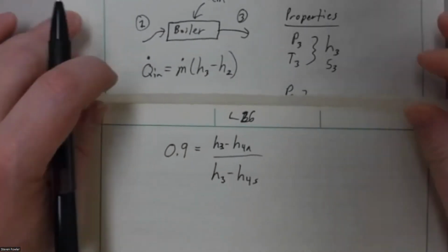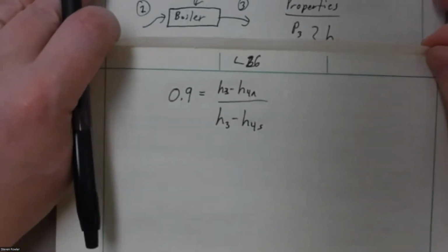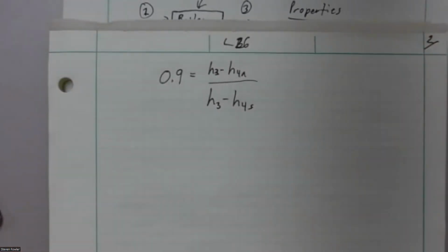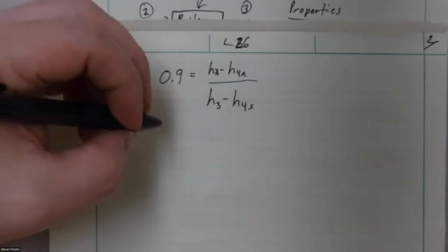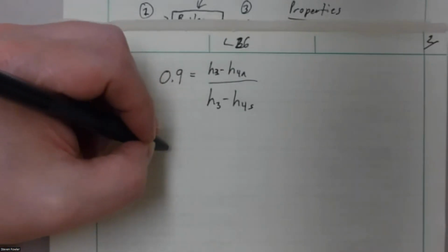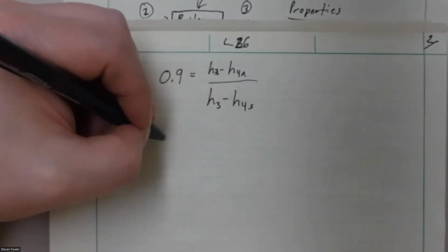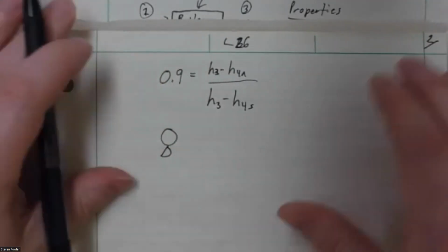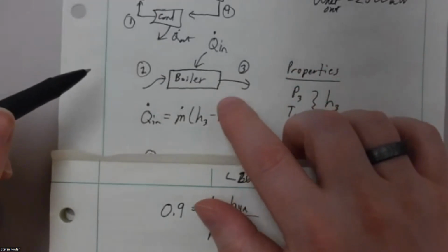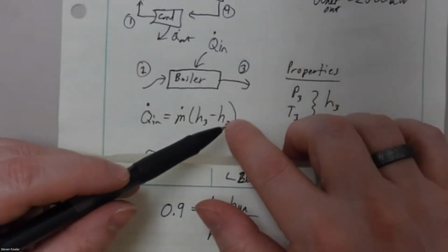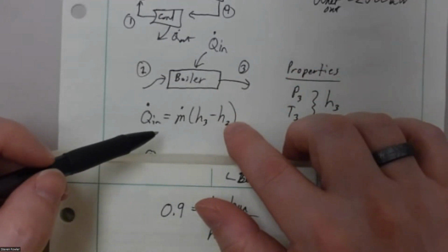Now, this is how a lot of times with the Rankine cycle you want to approach it: just start looking at the individual elements. What can I find with the individual elements? Does that get me a clear path back to a final solution? Mathematically, it's not a lot more complex than what we've already done. It's just that now I've got 4 different states I'm processing, so I've got to try to keep them straight. If I look at the pump, for example, I'm going to have to find H2 to get to either Q dot N or M dot, one of the two.